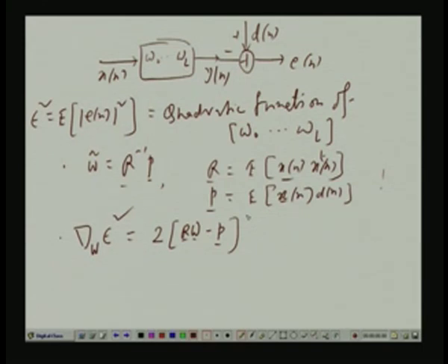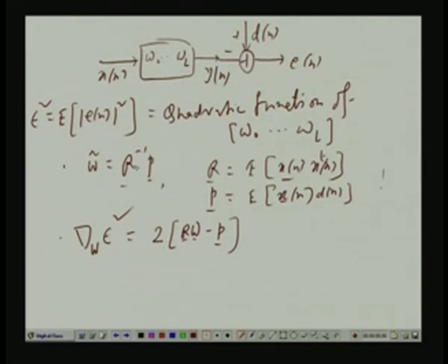This you have seen. Now, one thing is that you can find out the optimal filter directly by R inverse P, but suppose you do not have to follow this path. Suppose you do not know how to compute the inverse of a matrix. We can propose an alternative method, which is an iterative method, so that as the iteration progresses, finally the filter weight W converges on what is called the optimal weight. We now propose an equivalent technique, that is an iterative technique, called method of steepest descent.